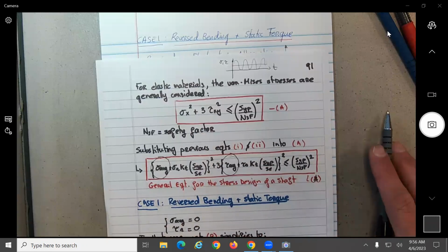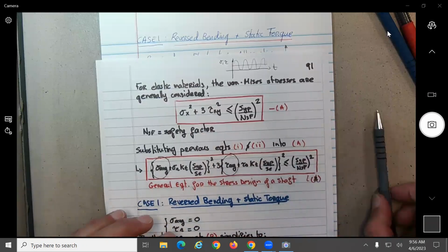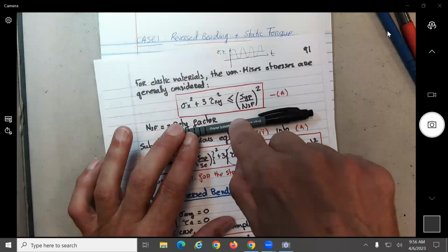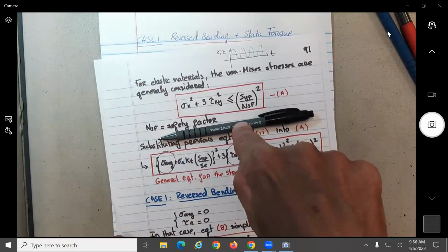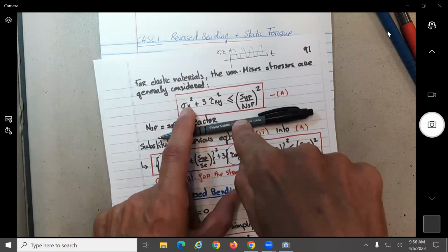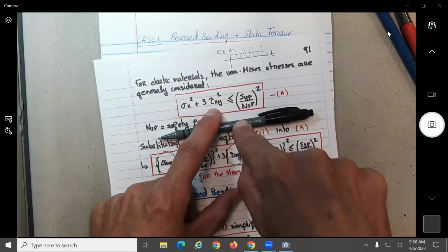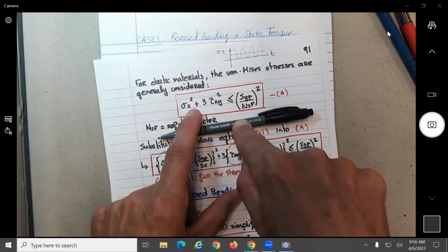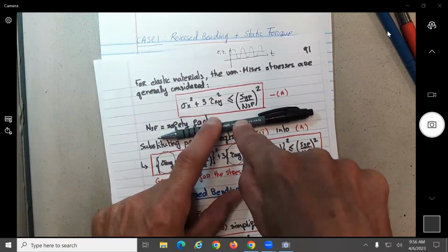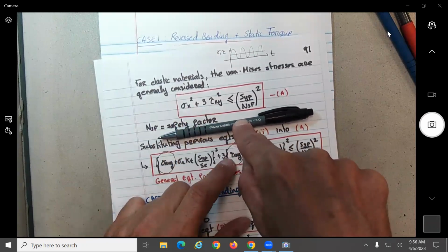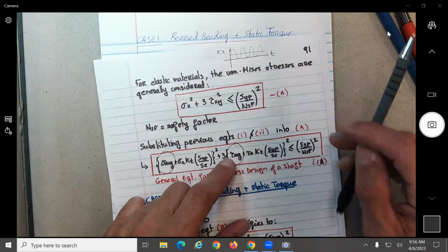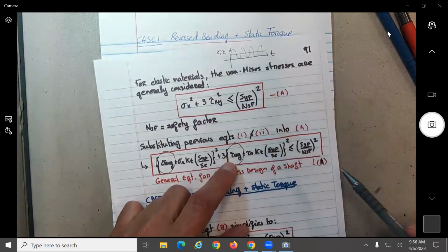That's what these average values are over here: initially there's an average force. For example, if you have a shaft, let's say initially there is a constant force on it. This will create a constant bending stress, an average normal stress, and also an average bending stress, no? That will be constant. And then the structure will be fluctuating between these values.